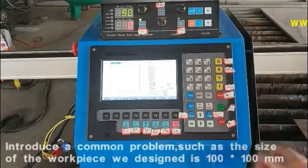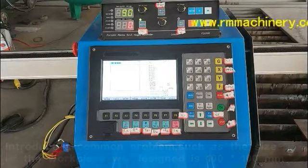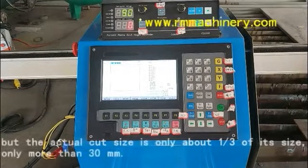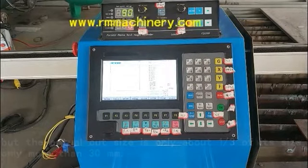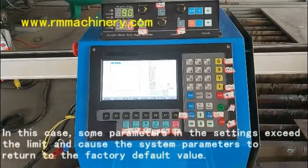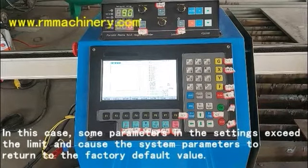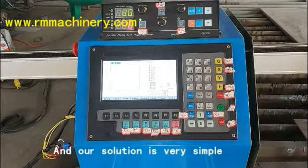Let me introduce a common problem. For example, the size of the workpiece we designed is 100 × 100 mm, but the actual cut size is only about 1/3 of that, only a little more than 30 mm. In this case, some parameters in the settings exceed the limit and cause the system parameters to return to the factory default values. Our solution is very simple.